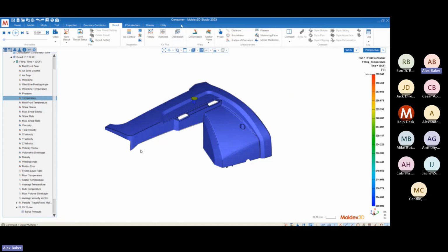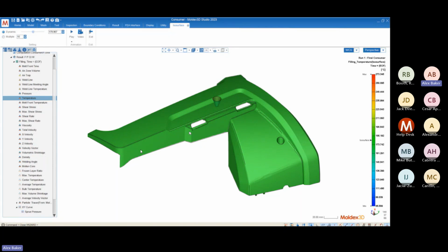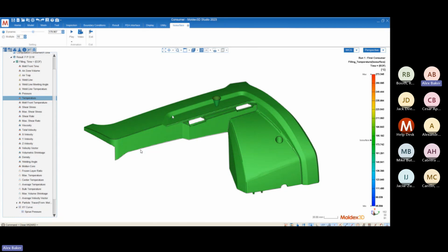All right, first thing, I'm going to close out of the slicing tool. I'm also going to reset my scale. To do so, I'm just going to hover over my scale, and there's a little toolbar that'll show up. There's going to be a reset display range that allows me to reset the extents of my original scale. All right, and just below the slicing tool is the isosurface tool. Isosurface allows us to break away all of the results in our display except for one singular value. And that's shown up at the top left corner.